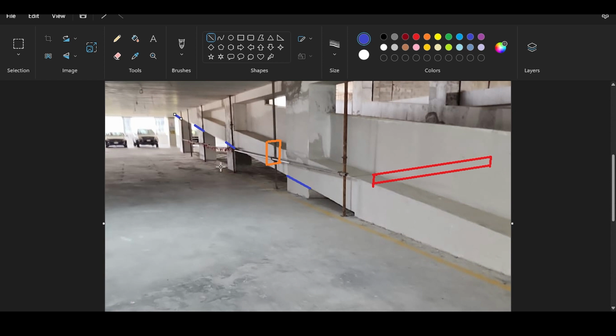So actually, you would have columns that look kind of like this. Now, not really inclined. Inclined is not a must here. You could, for example, cast the columns all the way horizontally until this place, and cast the rest with the beam. That's not an issue. But the point being is that it needs to be set out. You would have columns that have different heights. Now you cast those columns, of course, with the other columns.